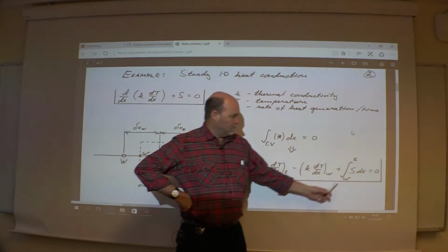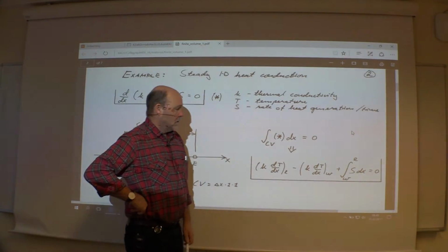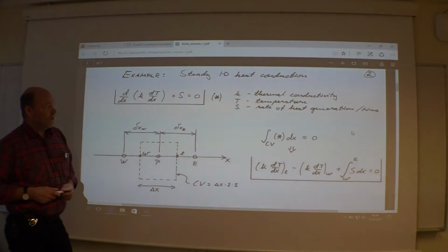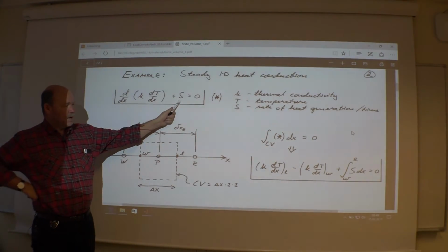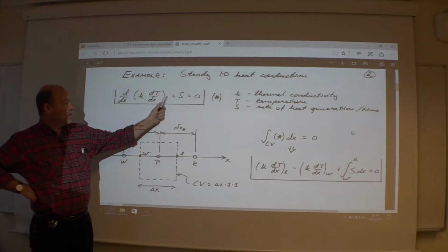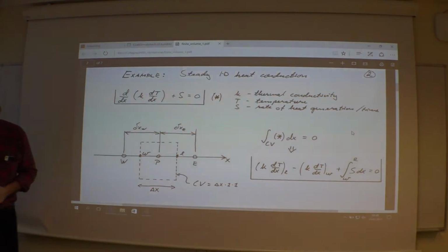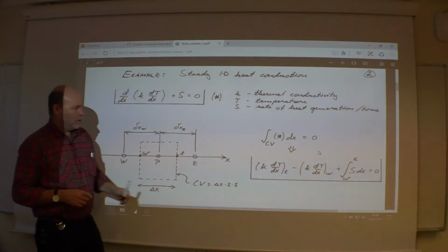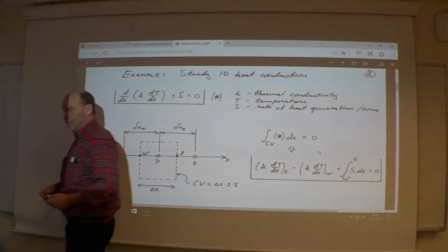The source term can be whatever it wants. It doesn't have to be constant, it could be a function of the solution, could even include derivatives for that matter. Normally it doesn't. Normally you have at the most linear variation with your unknown, whatever that might be. So we have to now make a choice. How can we express these derivatives at these boundary phases?